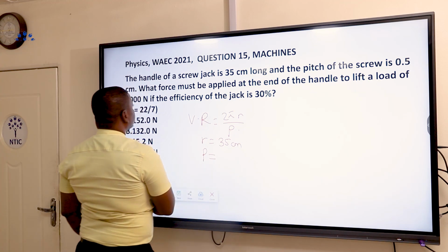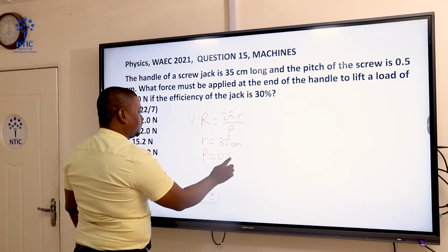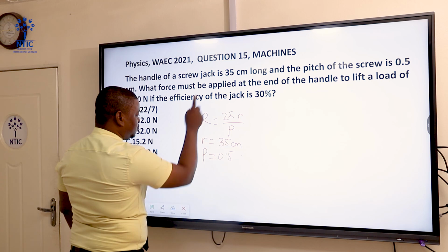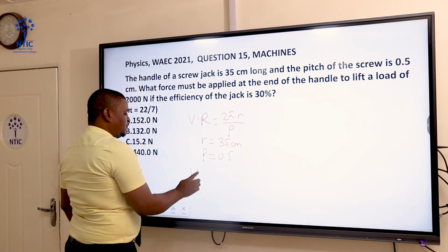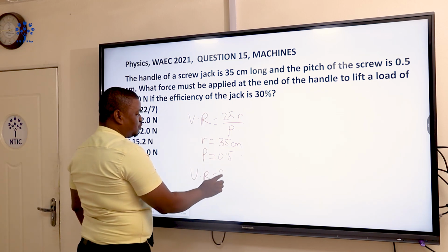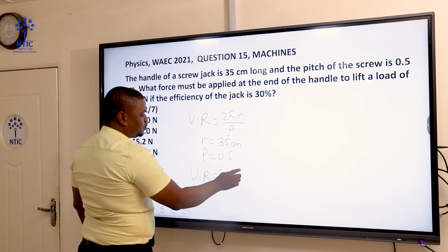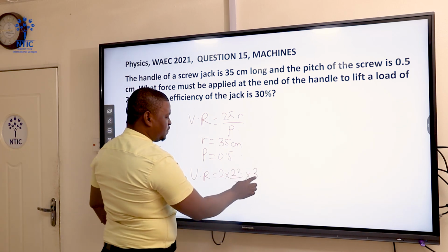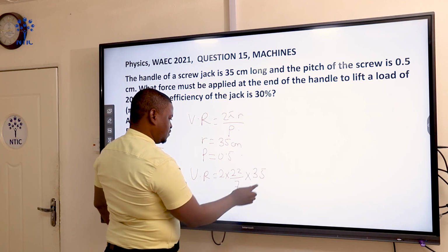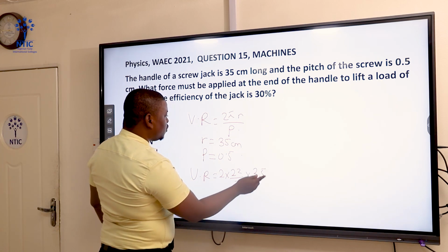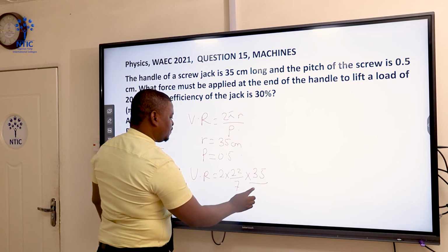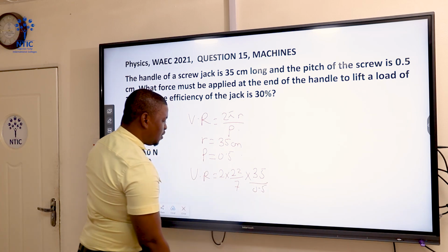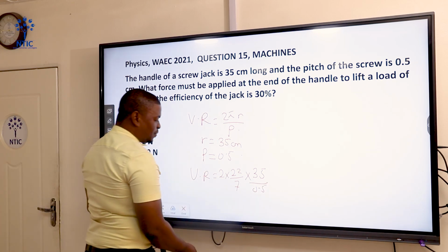my pitch is 0.5. Now, if I substitute, I'm going to have VR equals 2 times 22 over 7 times my R, which is 35, over 35 divided by 0.5.